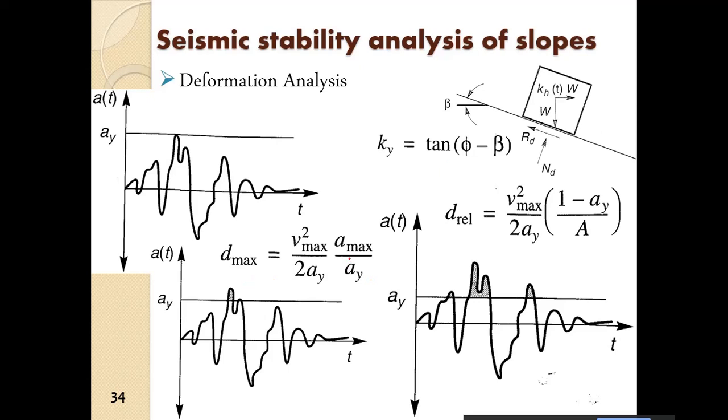Then we find out the maximum relative displacement. We see that the relative displacement of the sliding block is ultimately dependent on the yield acceleration. If the yield acceleration is above Amax, there will definitely be no deformation.